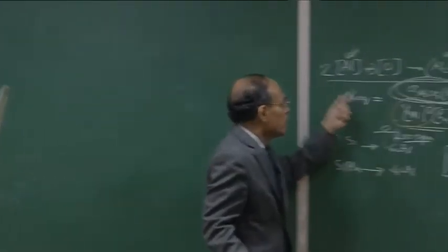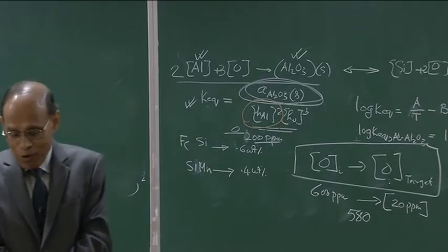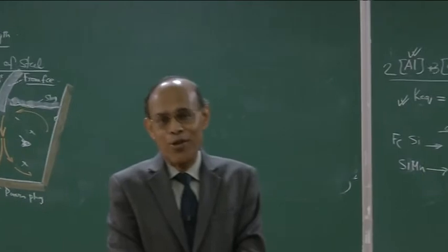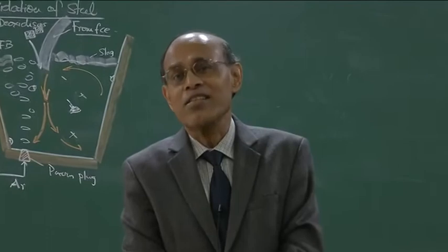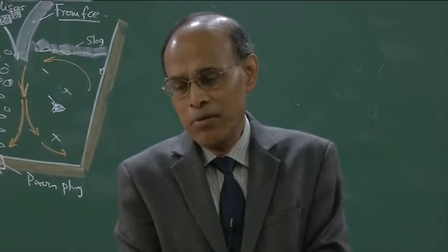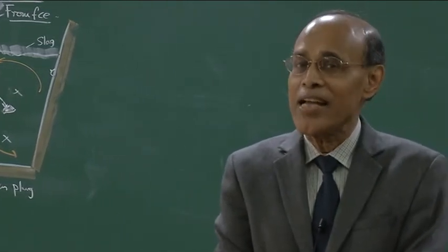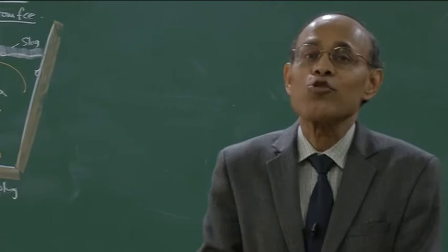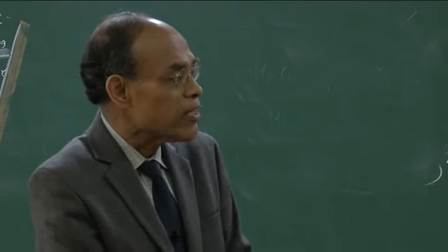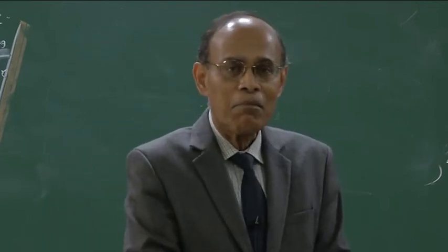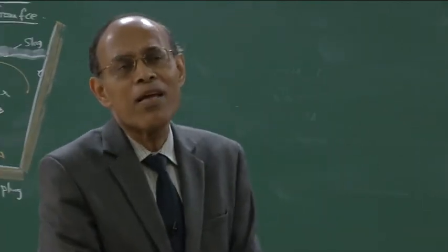this calculation rests on the assumption of an equilibrium, and I would say that an equilibrium is going to be very likely in the context of deoxidation reactions, because temperature is high, so the rates of reactions are going to be very fast. Also the melting and dissolution is not going to be slow, they are going to be very fast because of the large driving force for temperature, heat as well as mass that I have already mentioned.